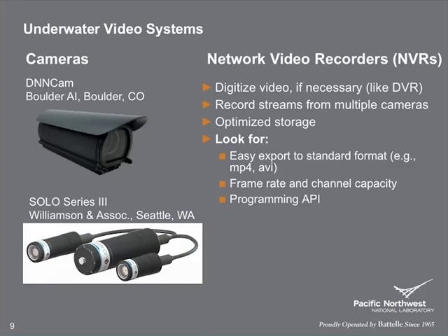However, when you're choosing an NVR, make sure that it's easy to export the recorded data into some standard format, preferably MP4, which is pretty universal, because a lot of times these network video recorders use a proprietary format that makes it difficult to work with except within their proprietary software. So make sure you can export that in a standard format.